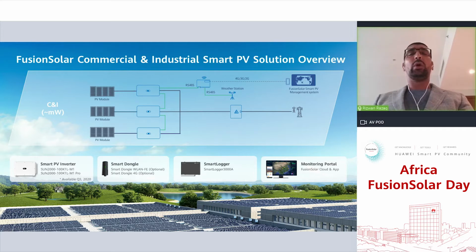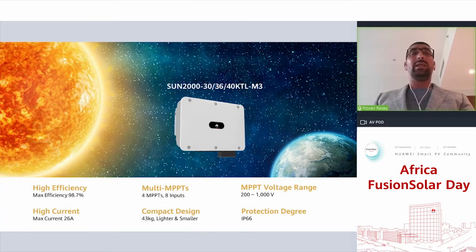Huawei is also offering the Huawei monitoring platform, which is called the FusionSolar platform, and that pulls the data directly from site and displays it on a third-party server, which is hosted, and then that information is available for our partners as well as our clients to access that data and configure with the products that are on site. So our latest product, as I mentioned, the 30, 36 and 40 KTL M3,